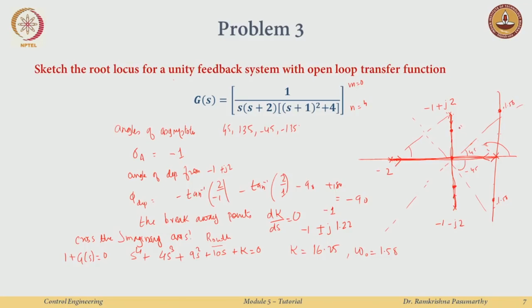Okay. So, now I know that it seems two of the roots will cross the imaginary axis. So, let us again try to analyze what is happening. This guy is going here and well, it is a breakaway point. So, he is just waiting for somebody else to come and meet him here, so that he could just say hello and go away. Similarly, this guy starts here, there is again a breakaway point, right. So, these are these complex breakaway points. Okay. So, these guys come here and this guy also comes here, they meet, right, and then say, well, okay, we have to go away because it is a breakaway point. So, this guy comes here, he goes and then they meet here, right. After this, well, they decide, okay, where should they go? They should go asymptotically along this line, right.